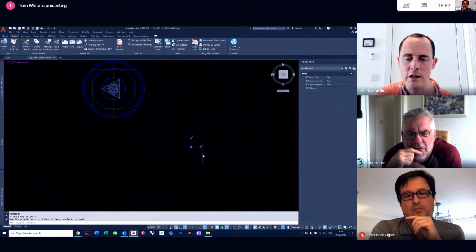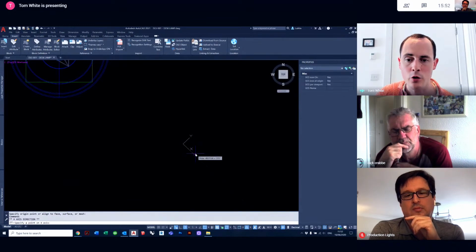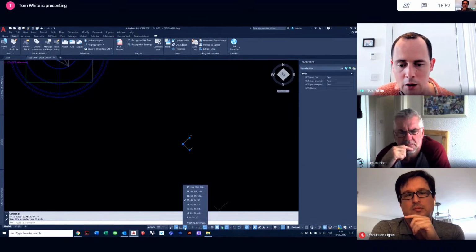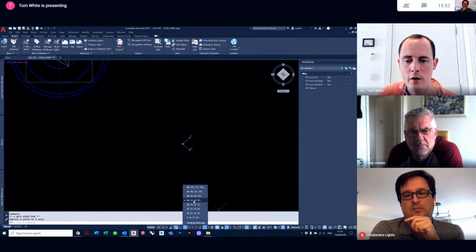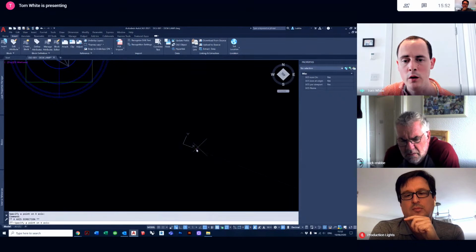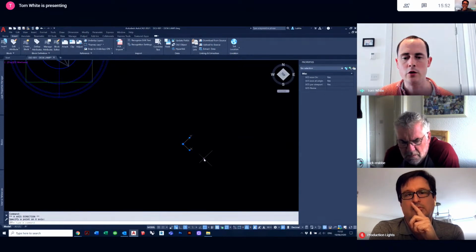On AutoCAD for the last 2 or 3 years, like we said, in theory, you could just copy it. Not copy it, move it, and then change it to your degrees. And the degrees are set down here. If I right click here, it's set at 22.5, 45, etc. degrees, and so it's locking to those. I know without doing too much guesswork, that's 90 or 0, and then this is 45 degrees.